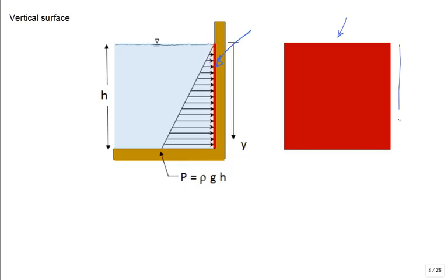So if you wanted to, this length is h, and maybe it goes into the board a distance w for depth or some other parameter. You can't see it, but it's into the board in that dimension w. Okay. So first of all, we'll look at just the gauge pressure, and it's a distributed pressure load. It's lowest at the top. The pressure at the top is 0 gauge. And the pressure at the bottom is the highest. It's rho g h. True? Rho g h.